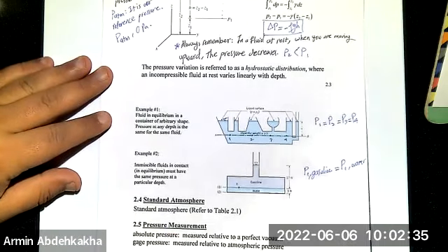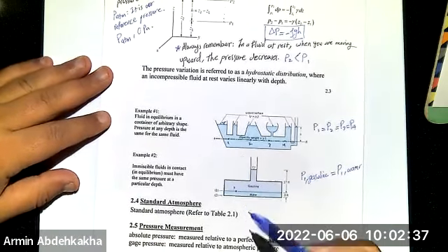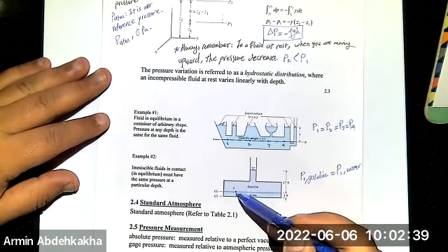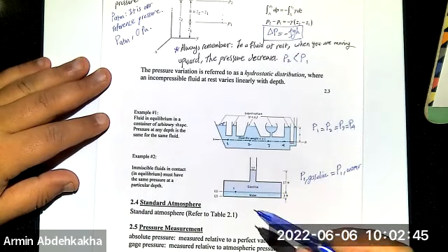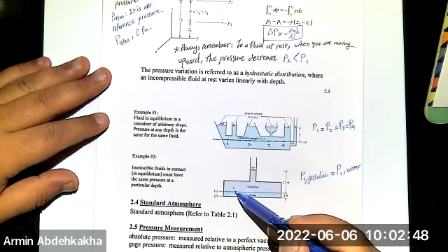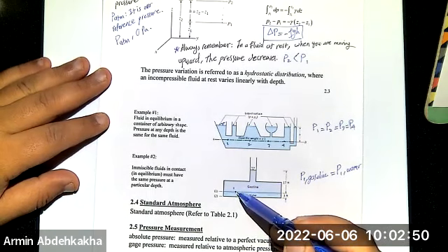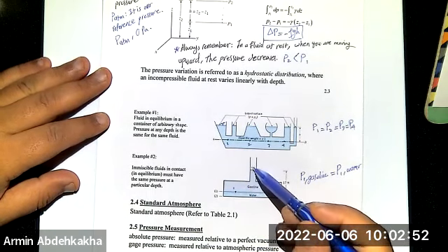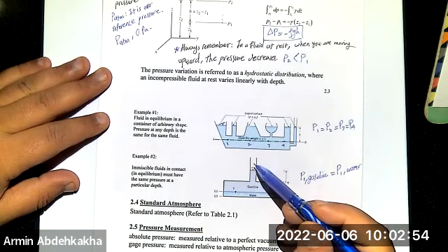This is also important. It doesn't matter whether you move to calculate pressure at point 1 from the upside or downside, these two should give you the same number, because the pressure at this point only depends on the depth, not the type of fluid that is at the top of it.